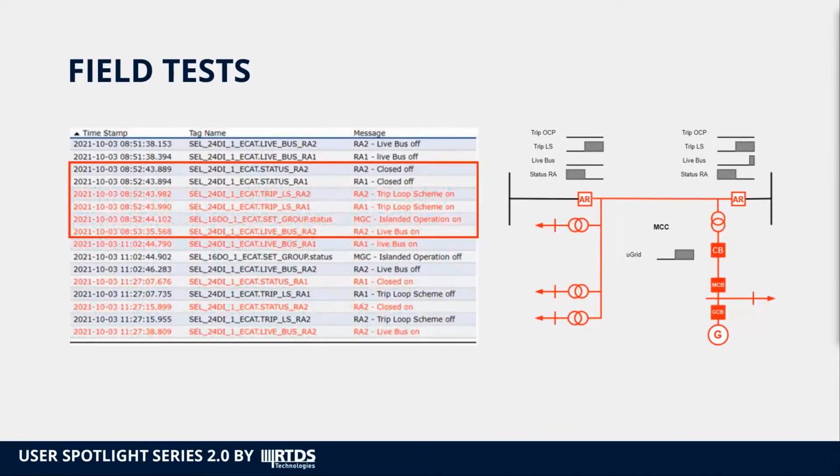After 1 minute without power, the reclosers signal the trip loop scheme, opening the circuit breakers and isolating the microgrid area. At that moment, all conditions for microgrid island operation are satisfied, so the MCC indicates this condition to the PSS and GCP.